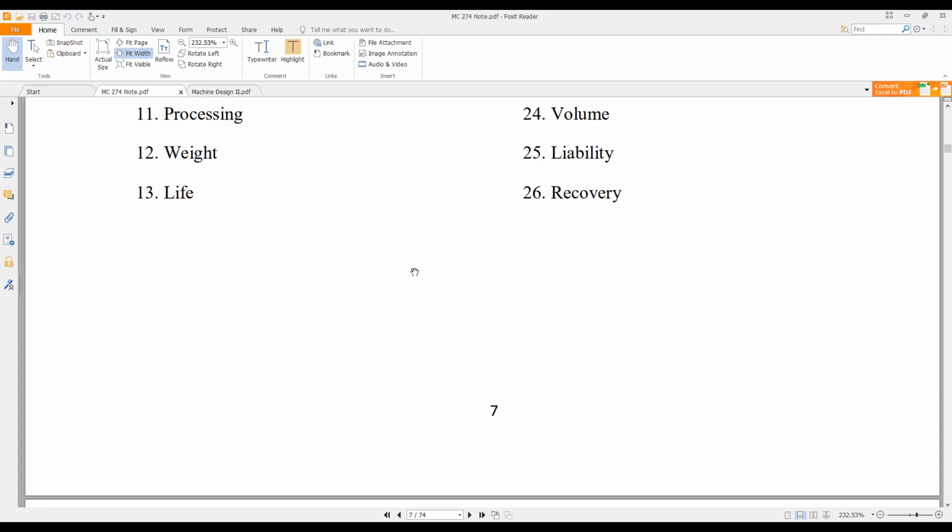If it's having, let's say, a sharp neck, maybe you have something like a cantilever beam. That cantilever beam, one side is free and the other side is matched to a wall. At the neck, where the bending moment is going to be very large, that's likely to fail there. So at times we provide what we call stress relief, like a fillet at the joint where it's merging with whichever member it is merging with, so that though there will be a buildup of stress there, it will not be prone to fatigue failure due to that fillet provided to relieve that stress.